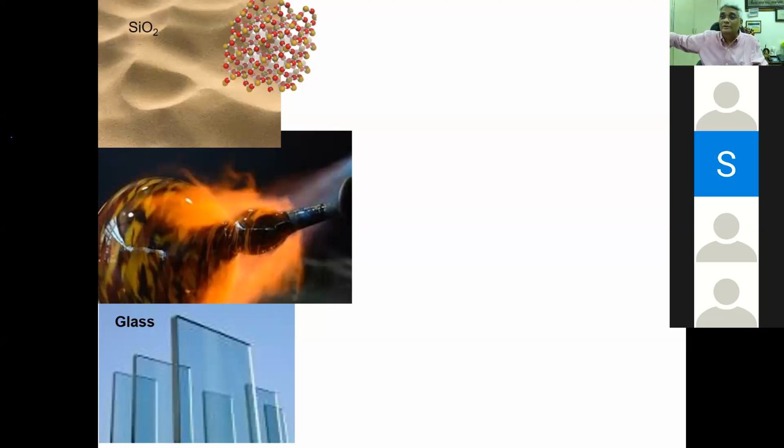Natural cooling from 1500 degrees centigrade takes about anywhere from 1 to 1.5 hours. And that much time is sufficient for atoms to settle down to their lattice positions. At least some form of crystallization happens, right? But if you don't want to give even that amount of time, just quench it. That is the actual definition of quenching: quenching it to ice temperature or liquid nitrogen temperature.